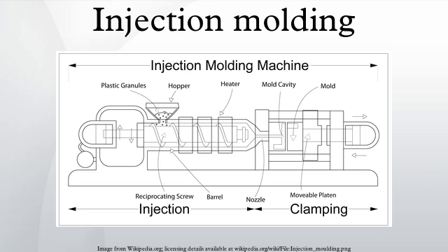Process troubleshooting. Like all industrial processes, injection molding can produce flawed parts. In the field of injection molding, troubleshooting is often performed by examining defective parts for specific defects and addressing these defects with the design of the mold or the characteristics of the process itself. Trials are often performed before full production runs in an effort to predict defects and determine the appropriate specifications to use in the injection process.